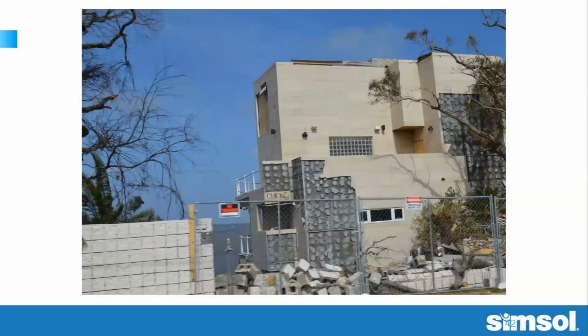And again, this is a different aspect. This is a concrete building that actually had the stucco in sections pulled off of it. And you don't see this very often. It's kind of unusual because where would we expect to see typical wind damage? At the top of the building, not necessarily at the bottom. But this building was up on a bluff, and it was struck by a water spout that came off of the bay and turned into a tornado. And as the winds rushed around the side, from the back side of the building around this corner, just like with a roof, you would have issues with the wind pressure picking up at the discontinuities and causing displacement.